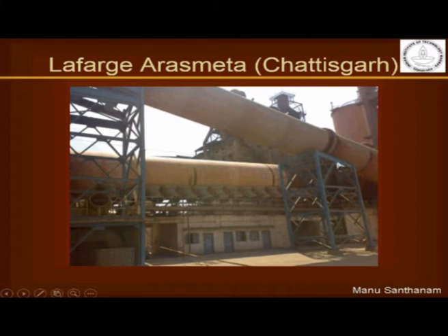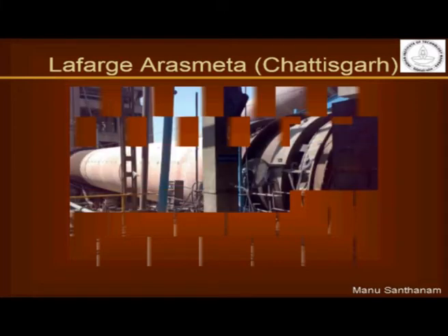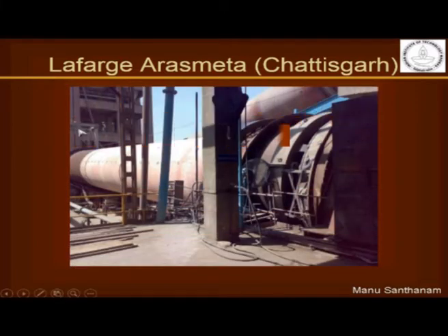This pipe that you see, which is of a large size in front of the rotary kiln, is actually used to carry the heat back into the system. The heat that is released or wasted in the process of clinkering is retaken and sent back into the preheating process so that you can improve the efficiency of the process. Now this is the rotary kiln again from the other end. The material comes in at this end and comes out at this end. So you can imagine that the fuel source is located at this end of the rotary kiln, where the maximum temperature will also be felt.